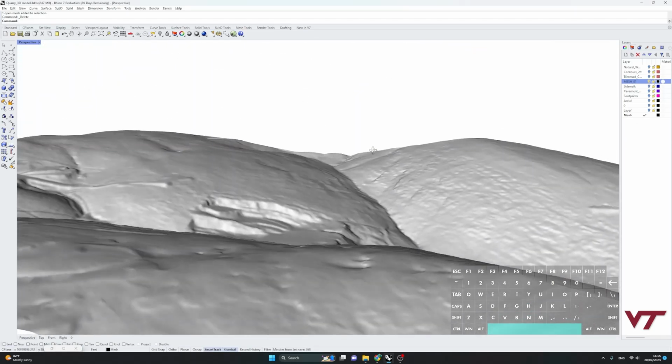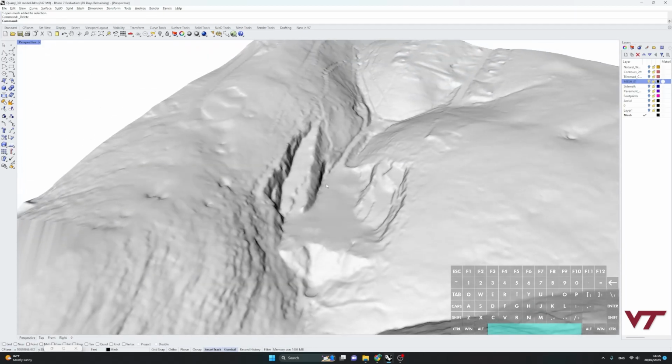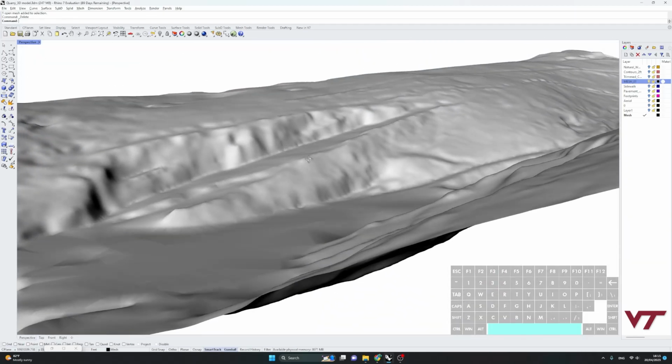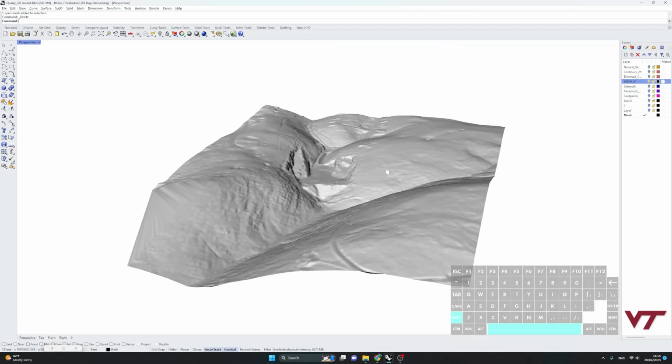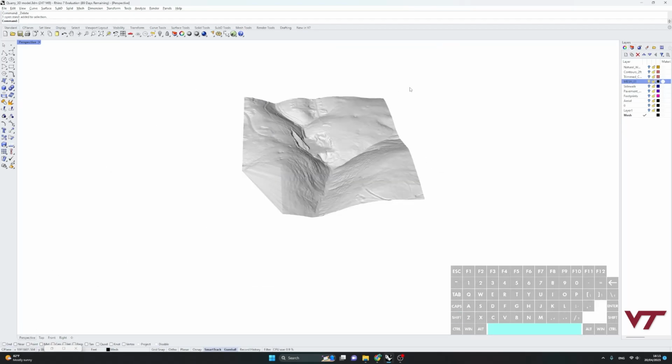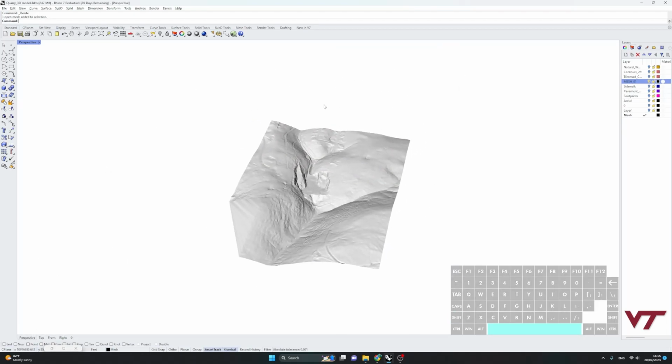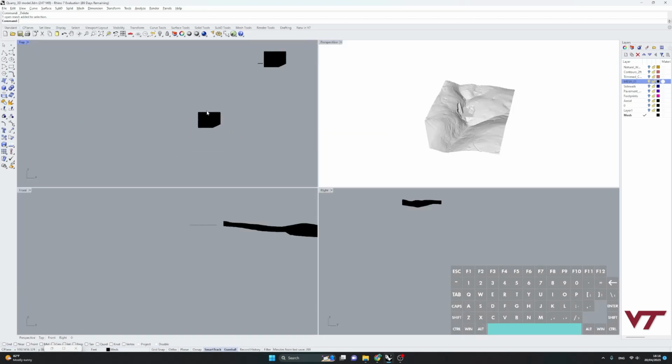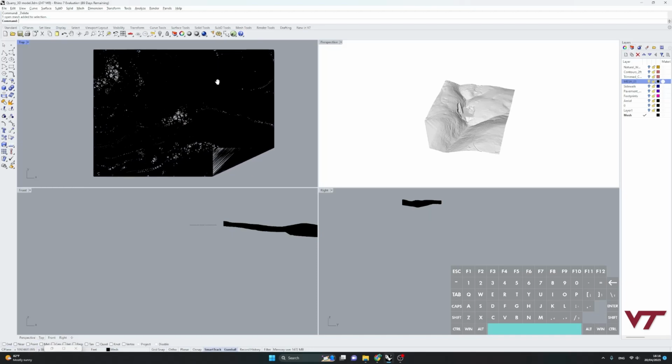It's not a huge difference, but it does make a fairly decent difference once you start getting down to this kind of scale in here. Now you can't really edit meshes all that cleanly, so another thing you can do is drop a surface on top of that. If we jump in here and use drape, basically draping a surface atop this.